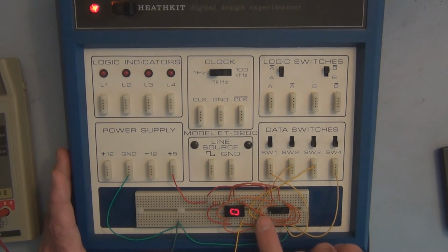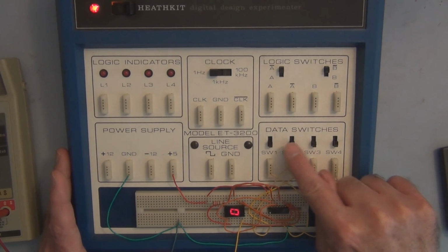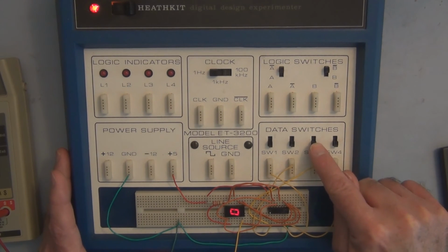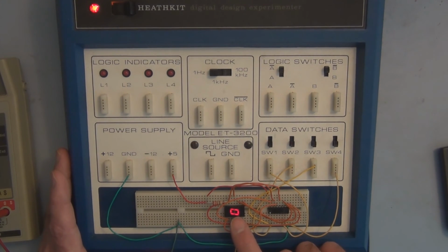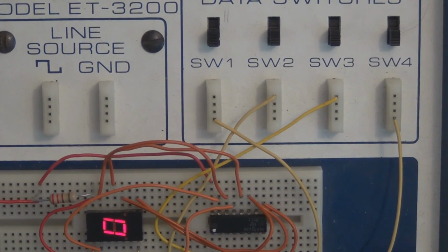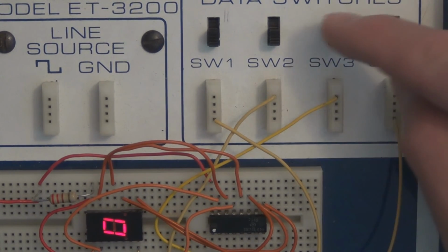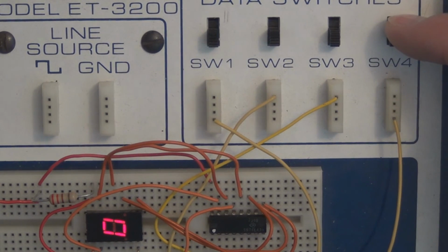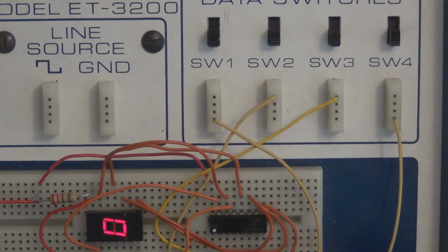When they go low, corresponding to these BCD inputs, they will light up the individual LEDs here to form the decimal symbol. So if we take a closer look, the circuit by default is already going to display the decimal 0 because your BCD code group starts off at 0. So you already have 6 individual LEDs lit right here.